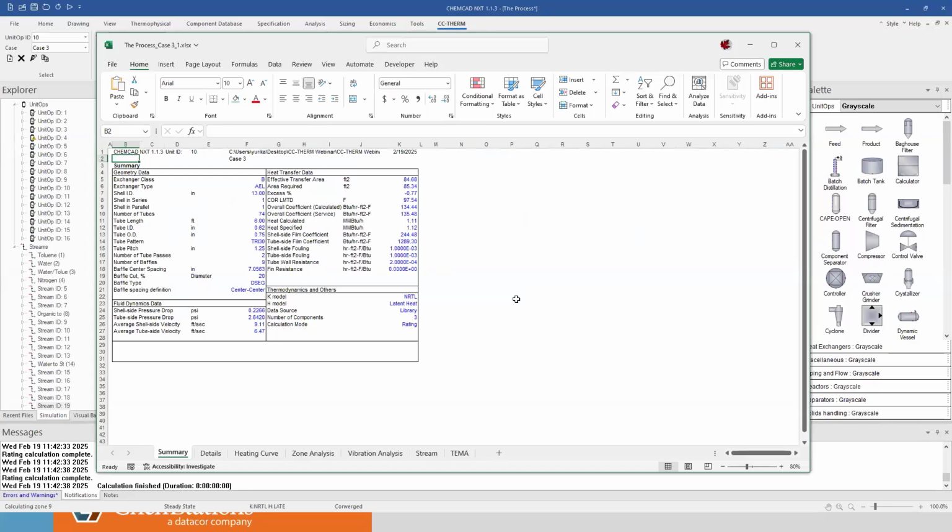So now, as you can see, I expanded. What I did was open up the tube bundle, okay? When I entered the pitch, I increased the pitch from 0.9 to 1.25. I opened up the tube bundle, right? And what happened here is that not only did I keep the limitations that we have, and we're still okay, but look what happens.